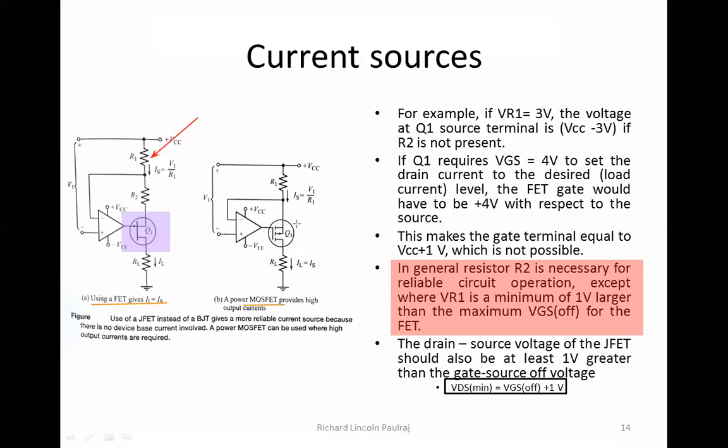And one more thing that you can keep in mind is that MOSFETs do have a lower power consumption than BJTs. So if you're thinking of power consumption, then MOSFETs could play a major role. The switching time between the highs and the lows, between ones and zeros, is faster in MOSFETs compared to BJTs. So BJTs are a little slower, but the load carrying capability is higher.